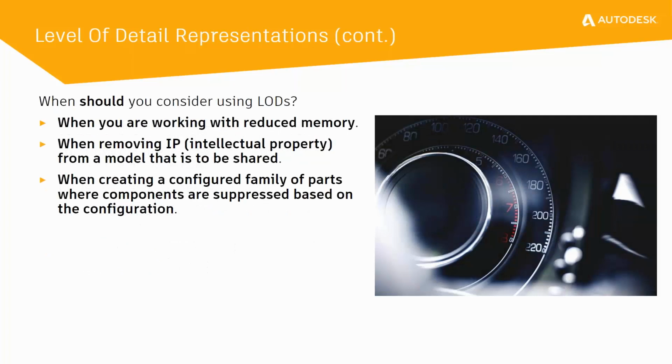So when should you consider using them? Well, you should use them when you're working with reduced memory. Maybe you don't have much memory to begin with, or maybe your system's running low on memory. Then level of detail representations can help. Also, when you're trying to remove intellectual property from a model that's going to be shared, it's a great way of doing that. And when creating a configured family of parts where components are suppressed based on the configuration, that's another good reason to use level of detail representations.